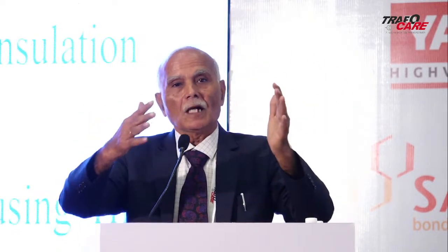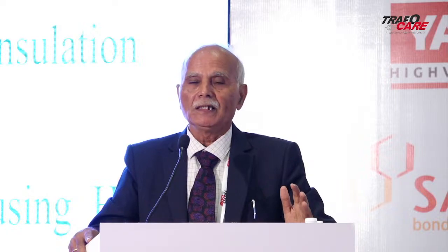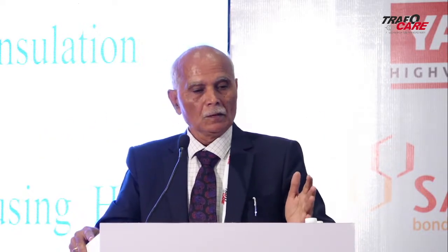So I appreciate the leading organization of our country, Power Grid Corporation of India, which is using furfural content and other techniques in a systematic manner by using software. And here, I am also requesting all other utilities to have a data bank, compile all the data and have their own artificial intelligence assessment techniques where the faults can be assessed and remedial action can be concluded by using the software. In fact, along with the other professionals in the country, we are planning to have such a database and even interpretation techniques made available in a group.